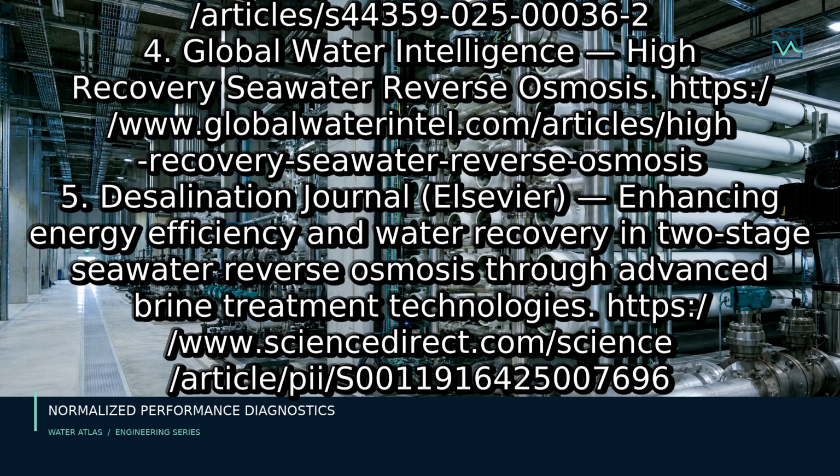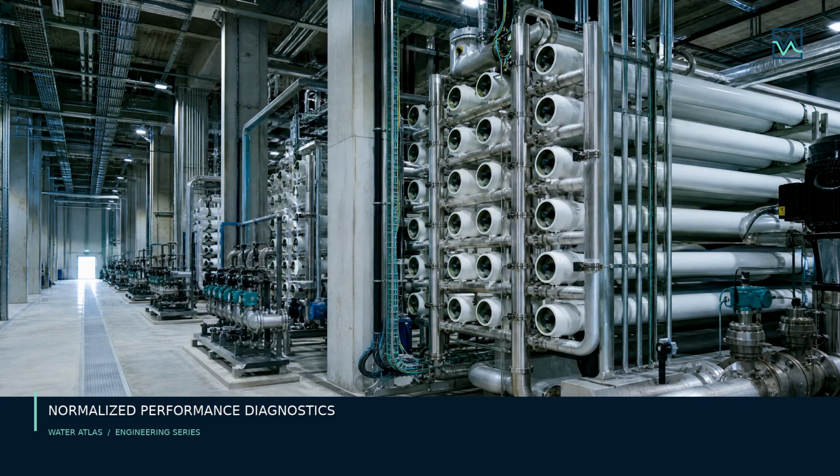While coastal facilities utilize engineered outfalls, inland facilities turn to minimal liquid discharge and zero liquid discharge technologies, combining brine concentrators, mechanical vapor compression, and thermal crystallizers. Even the most advanced SWRO design will fail prematurely without rigorous operational control, tracking normalized permeate flow, salt passage, and differential pressure across membrane stages for early failure diagnostics.